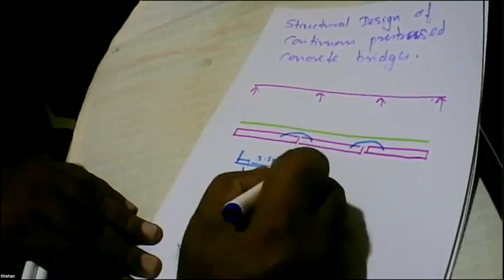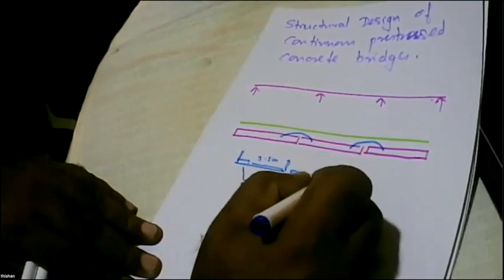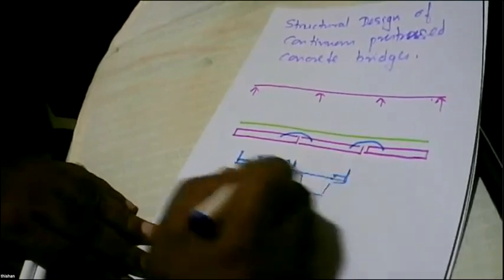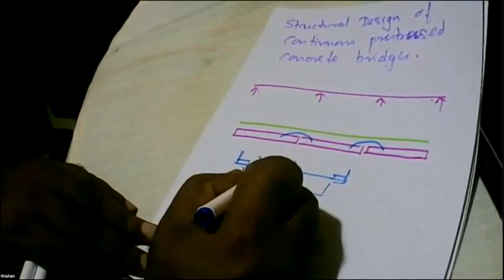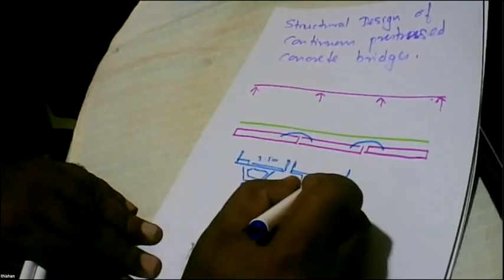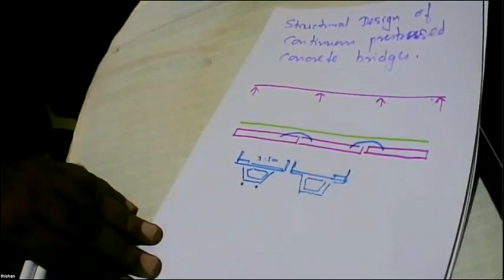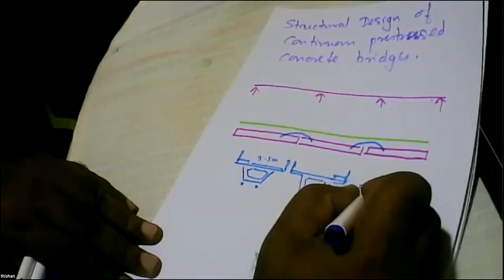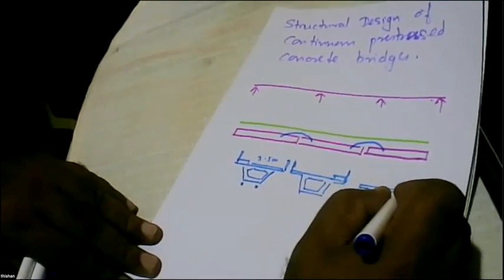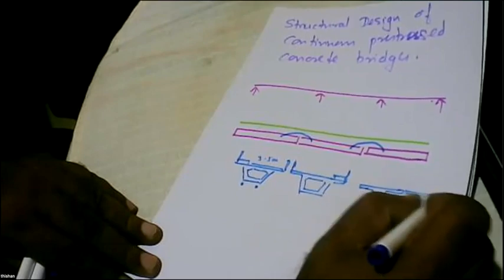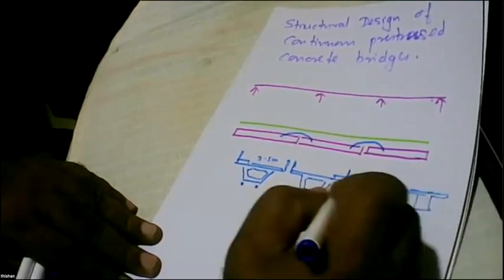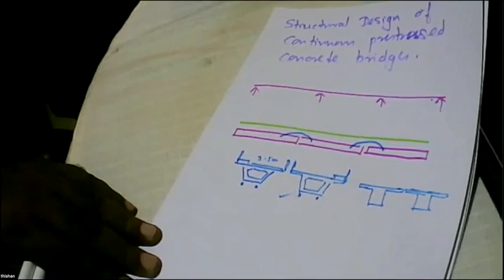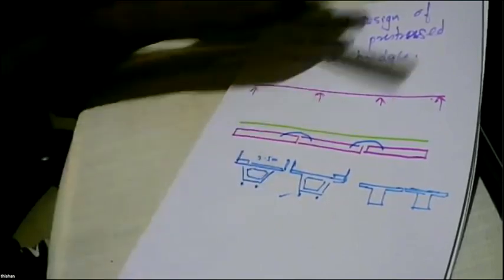and we can have another bridge side by side. And here again, there is a possibility. And here to make the weight minimum, we remove the concrete in the center. So we get box girders, and similarly we can also have T-type bridges. We can have 2 T's. Now that's another possibility. This is another possibility, but this is more common or more popular these days because people have mastered various things.